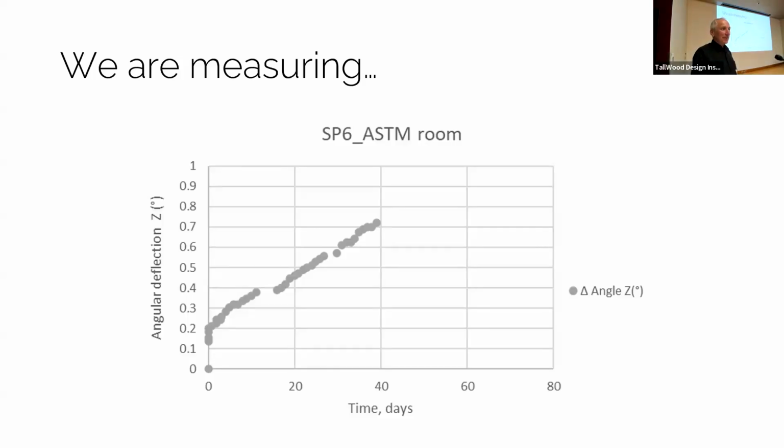Now, this is creep, don't hold your breath. We've gone through 6 specimens, out of which this is only the second one that actually creeps rather than breaks within an hour or two or during the loading. The torque that we put on it is pretty substantial. This is by design. We want our results quickly as far as creep is considered. And this is, as I said, don't hold your breath. This is where we are, right? Actually, we are right now at 60 days of testing of the 6th specimen.